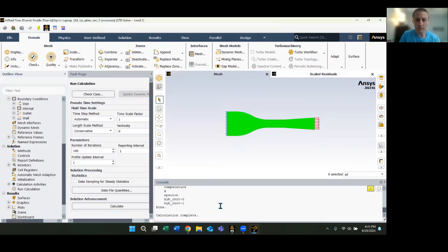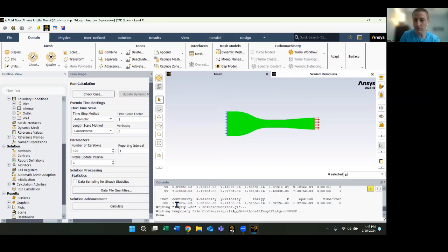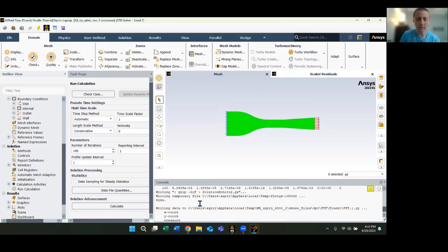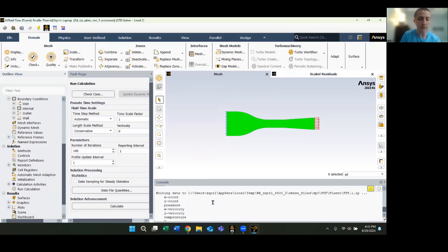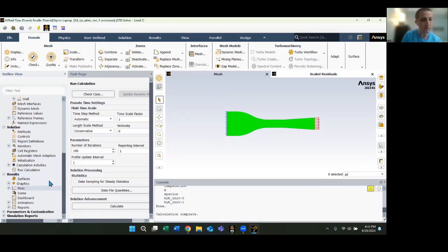All right, calculations are complete. You can check this did not converge, so we used all 100 iterations here. This was the 30 hertz frequency when we were doing it, so the velocity even in the project didn't converge, but if we did the 10 hertz, it was converged. But this one also did not converge, so we are good to go though.